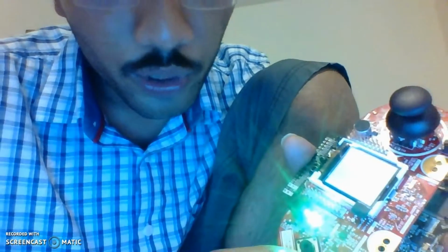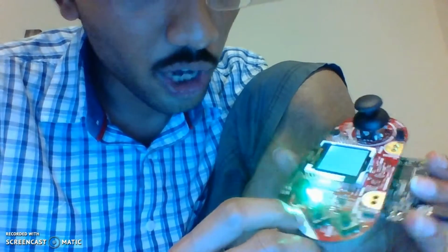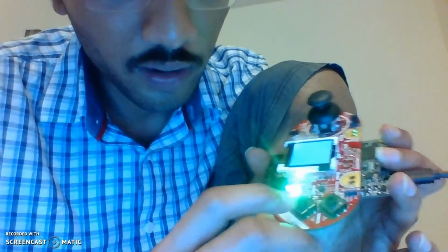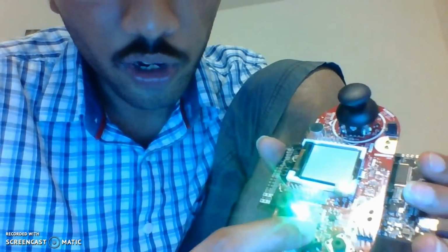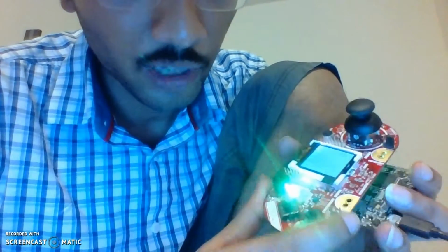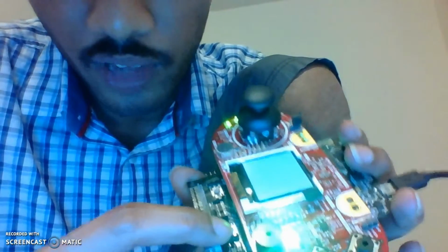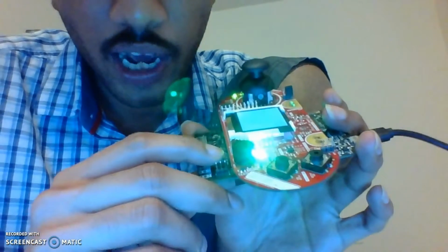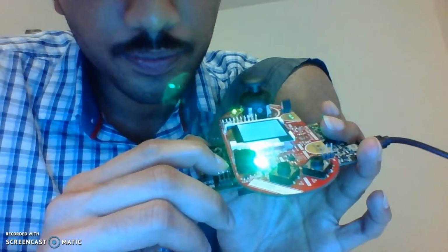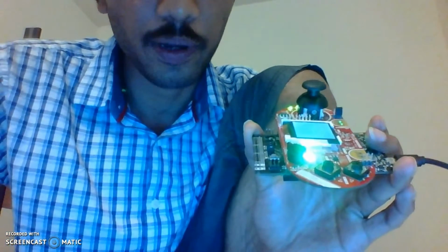Now you hear a fire alarm through the system, and the only way to stop the fire alarm is to press the reset button. Even if you press the doorbell right over here, it's not going to stop. And even if you go and shout near the board, hello, hello, hello, it's not going to give the burglar alarm because the fire alarm is the highest priority. And the only way to stop it is to press the reset button, the S2 button of the MSP432 board. So let's go and press the button. Yes, now it has stopped the fire alarm.